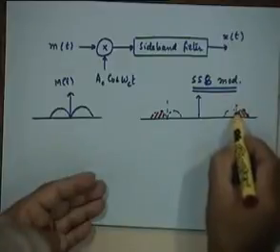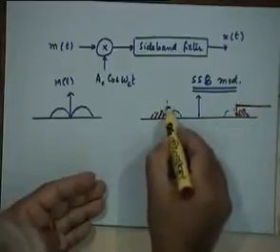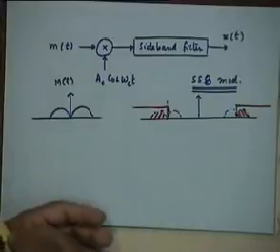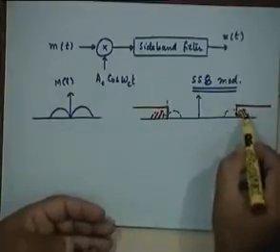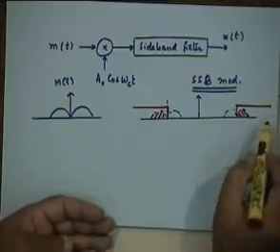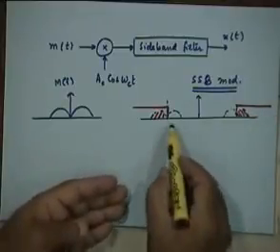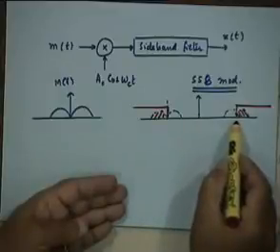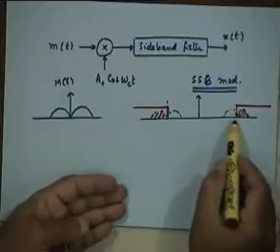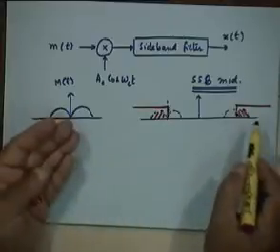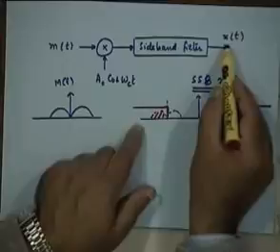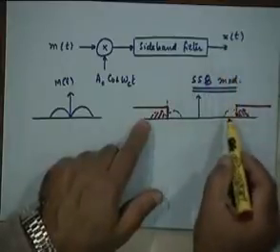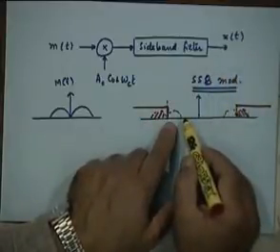So you require a filter with this kind of characteristic, right? Whose transfer function is 1 for |f| greater than f_c and is 0 between minus f_c and plus f_c. Is it clear? For |f| greater than f_c, the transfer function is 1, so it will pass this spectrum to the output, and the other spectrum will get attenuated, suppressed, eliminated, right?